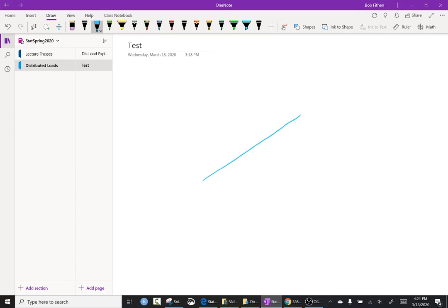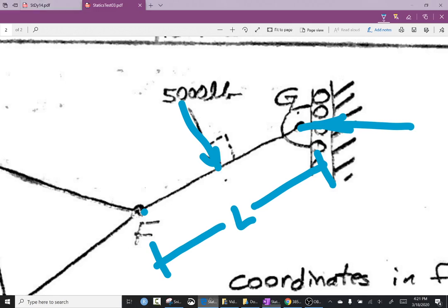Now, let's go over here and look at a beam. I'm not saying that it's exactly the dimensions, but let's just say you had a situation just like that, where there is no vertical load here. That doesn't exist. This point of the beam can move up or down freely. The 5,000 pound actually does something quite interesting. It wedges this beam down, so as this moves down, this force pushes against the whole structure.